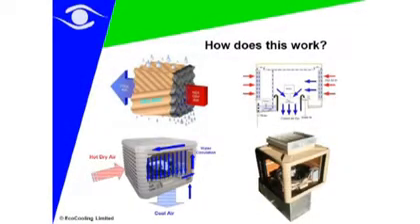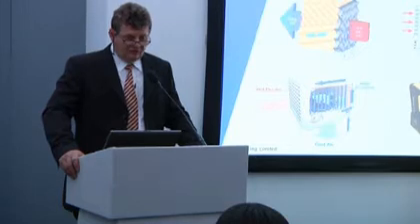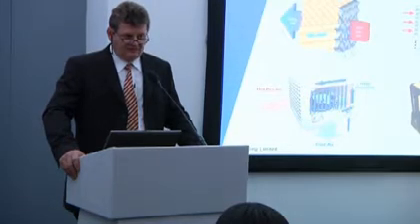How does it work? Well, it's no more complicated than air and water and their relationship. In the UK, when it is hot, the air is also low in relative humidity. And air is like a sponge. It loves to soak up water. If we put this air in contact with a wetted filter pad, water will evaporate into the air stream.